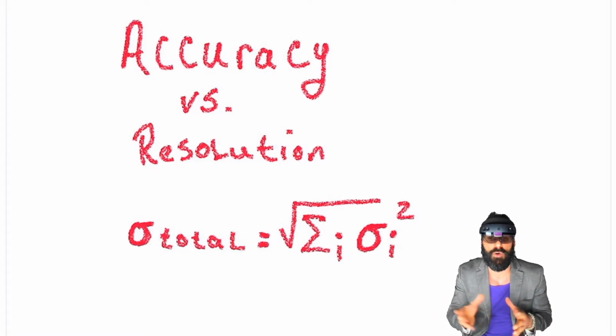But that input voltage range is partitioned into a discrete number of values the converter can measure, which is also the ADC resolution. So we have to look at the quantization error. In this case, it is specified to mean no more than 50% of that LSB, the least significant bit. So for the 12-bit ADC, analog to digital converter, the error rate is plus or minus 1.22 millivolts, or 0.0122%.